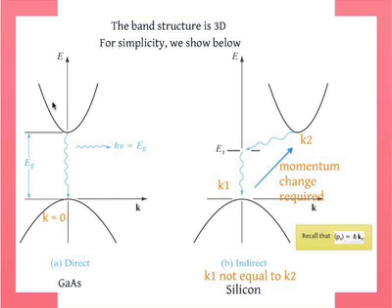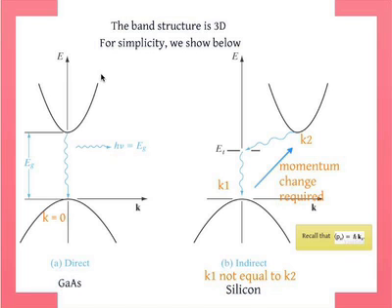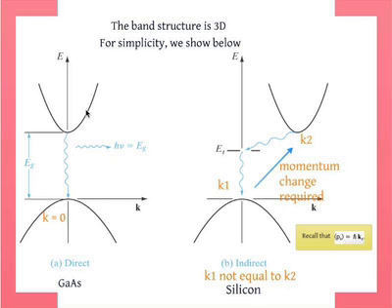The next few things to concentrate on. We see 2 bands. That's the valence band, and instead of having a straight line, now we have something like a parabola. And that's the conduction band. Again, instead of having a straight line, we have something like a parabola. It essentially means that as the electron momentum increases from 0, your energy increases faster than linear, which of course makes sense because remember that also includes kinetic energy. As momentum increases, kinetic energy has to increase.